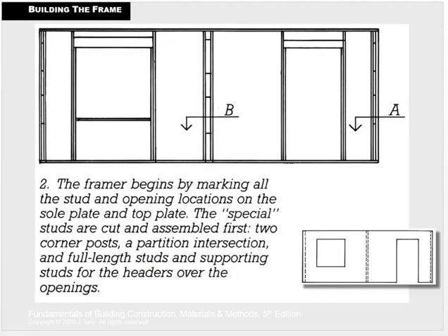So what the framers will do is mark all of those locations on the top and the bottom sill plates. Then they have to create certain framing conditions to accept those walls. So this is a corner post. So this is where an interior wall meets the exterior wall, and we're going to look at these in more detail. And another exterior post. And then the doors are framed in and the windows are framed in. So that's the next step on their list to do.